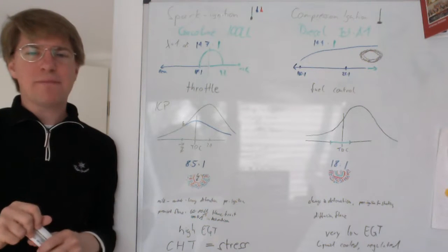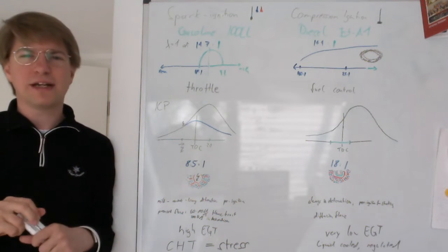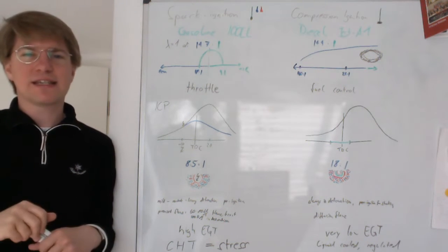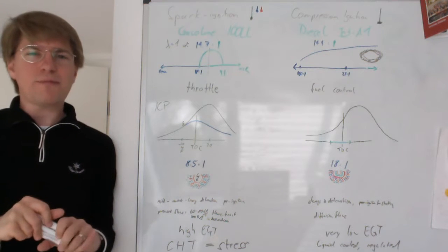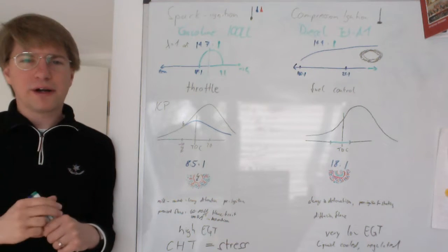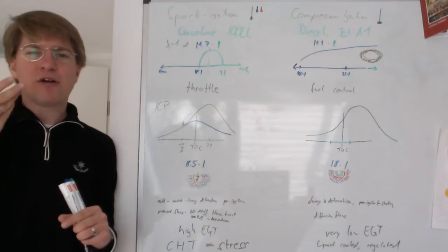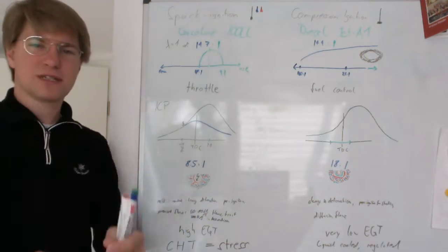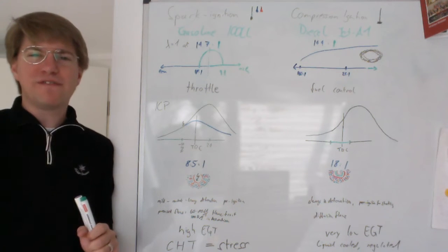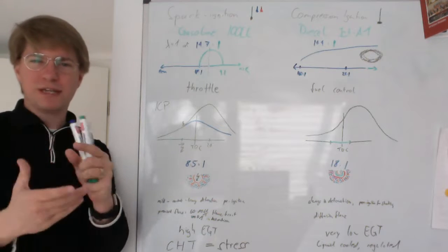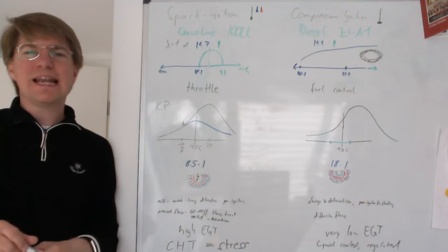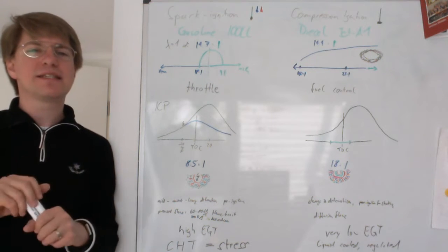And this is what happens if you were flying a normally aspirated engine, so an engine that has no turbocharger, and you fly it up into the flight levels as high as it will go, and you never touch the mixture control. Because what happens there is the partial pressure of oxygen gets lower. The piston goes down, sucks in the ambient air, and the volume is given by how much the piston moves and the bore of the cylinder. With each volume, we take in less weight of air because the air is less dense.